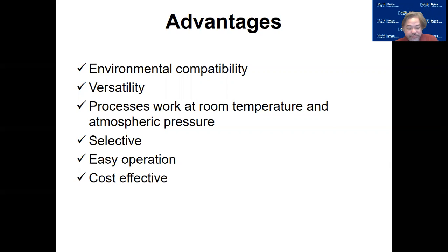So volumes of fluid from microliters to thousands of cubic meters can be treated. And in terms of selectivity, the applied potentials can be controlled to selectively attack specific compounds. So you just adjust the potential that you apply.